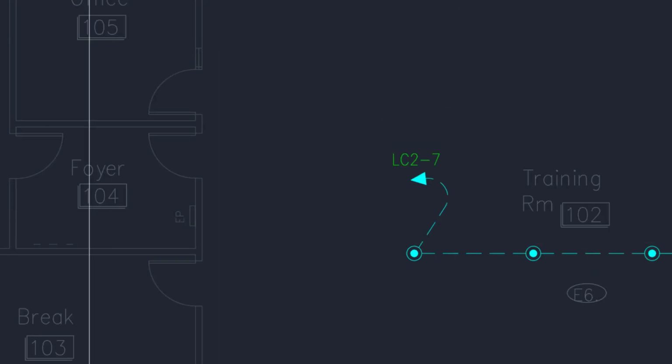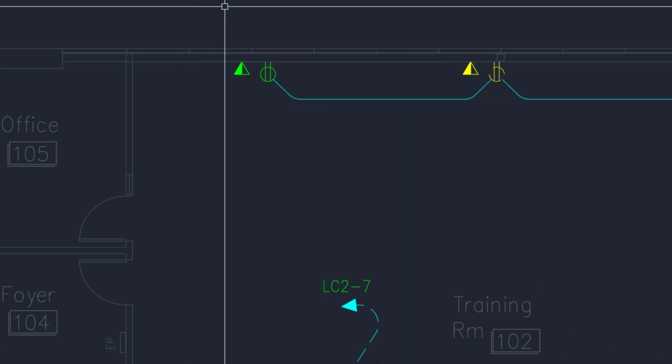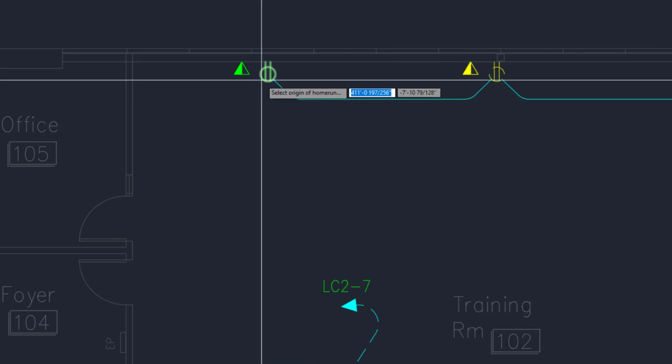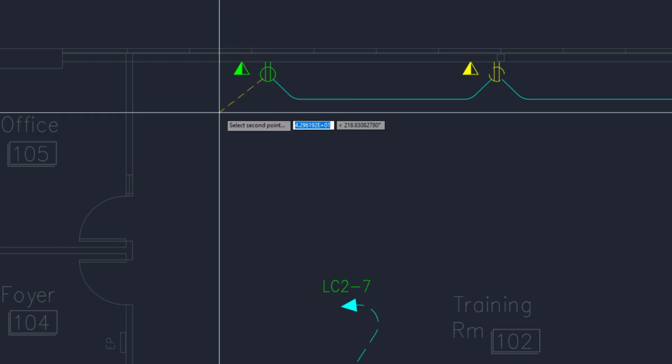So now that I'm set draw status new or existing or demo, the home run looks like this. So I click on it, and it wants to be by the outlet, and it snaps there.